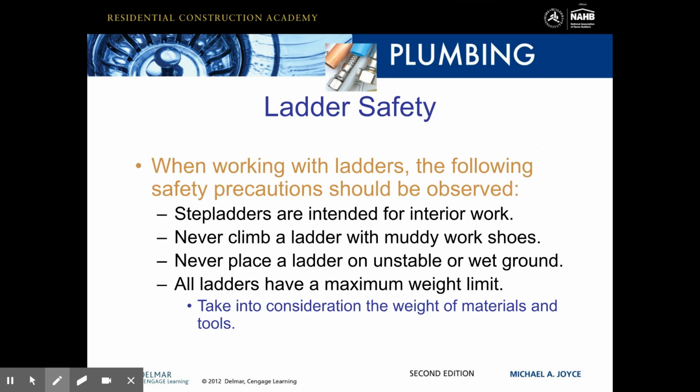When working with ladders, the following safety precautions should be observed. Step ladders are only intended for interior work. Never climb a ladder with muddy work shoes. That creates a slipping hazard. Never place a ladder on unstable or wet ground. All ladders have a maximum weight limit, so before you climb it, take into consideration the weight of the materials and the tools that you're going to be carrying up the ladder.